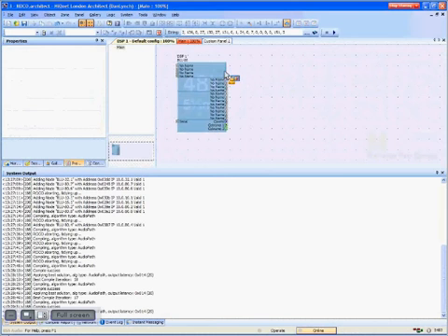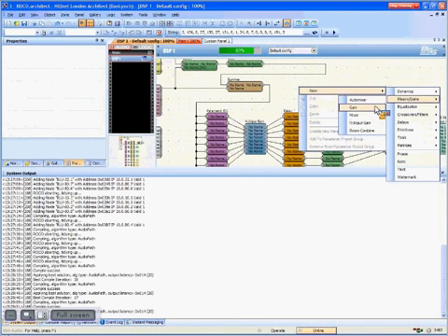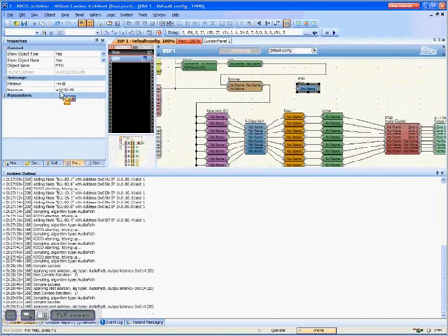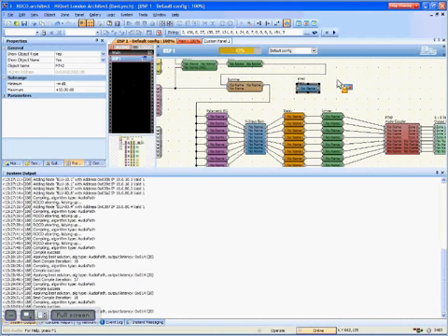Well, now the gain object, it's the only one that does it, but that's the one you need it to do. The gain object has a subrange right on the processing object. So you can tie it to an external control port, have it subrange limited, so you can say, okay, the customer can turn the volume up to 0. You can't turn it up past that. Or they can turn it down to negative 40. They can't turn it down all the way. One of those features that you really don't care about unless you bumped your head against it in the past, in which case you're sitting at your desk right now going, yes, this is awesome.